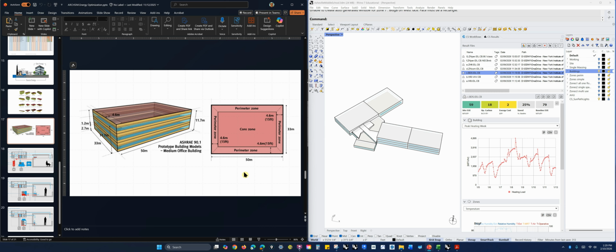It might just be, like in this system, we have these VAV boxes. As long as I've got a duct going into a room and a VAV box, I can adjust, so I could have one branch duct with 15 of these VAV boxes coming off it, and those could all be zones because I can adjust the temperature coming into the room or the area with that VAV box.